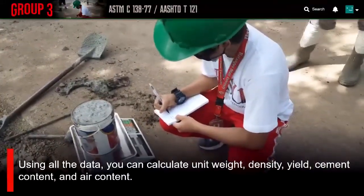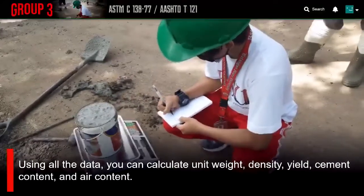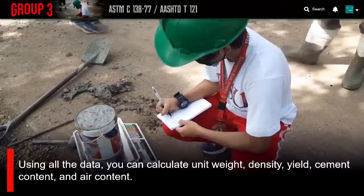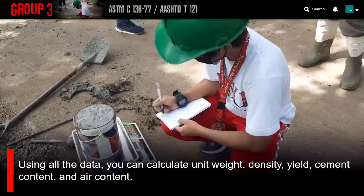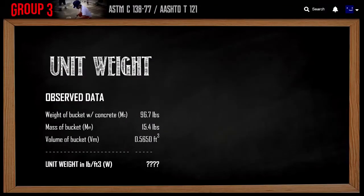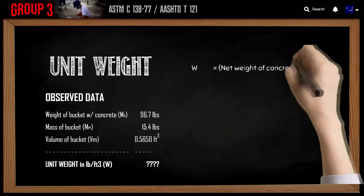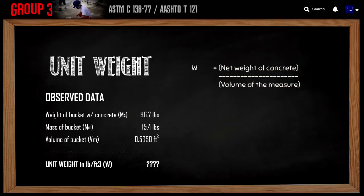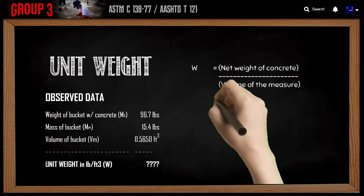You can calculate the unit weight, theoretical density, yield, relative yield, cement content, and gravimetric air content. Now let's go over the calculations. So first, let's define what unit weight is. Unit weight is the weight of the concrete per given unit volume. Now, to report the density or unit weight, we want to report it to the nearest 0.1 pounds per cubic foot. We do this by using the following equation.